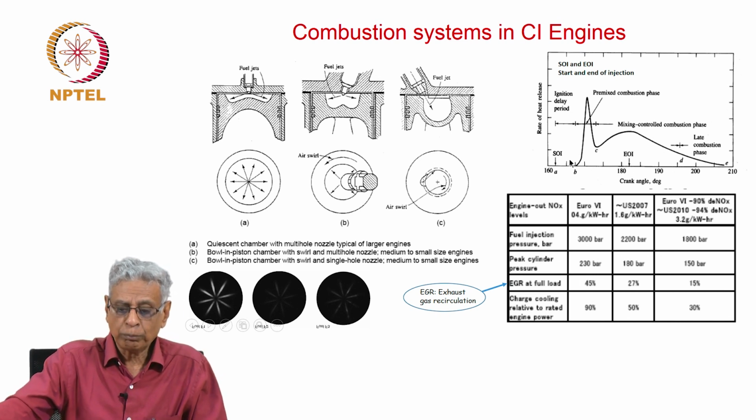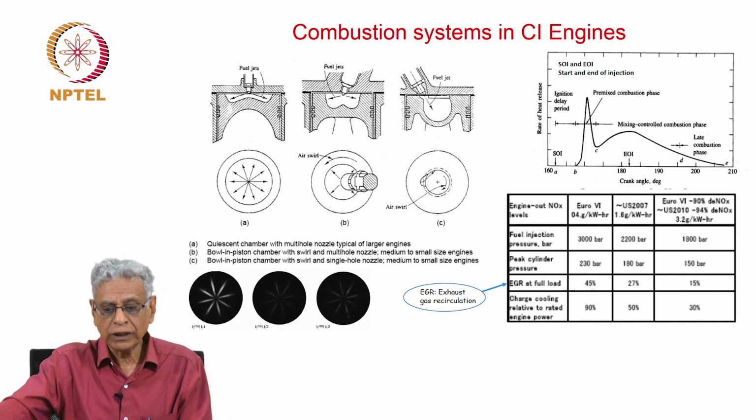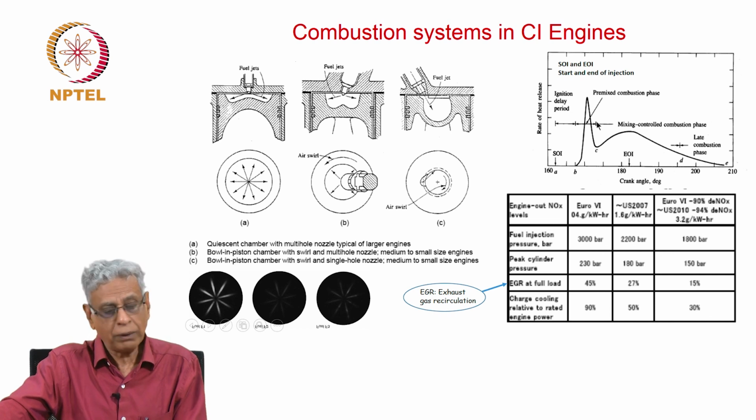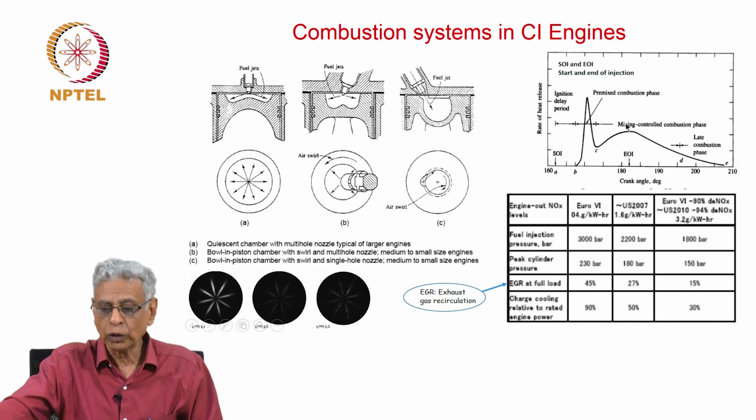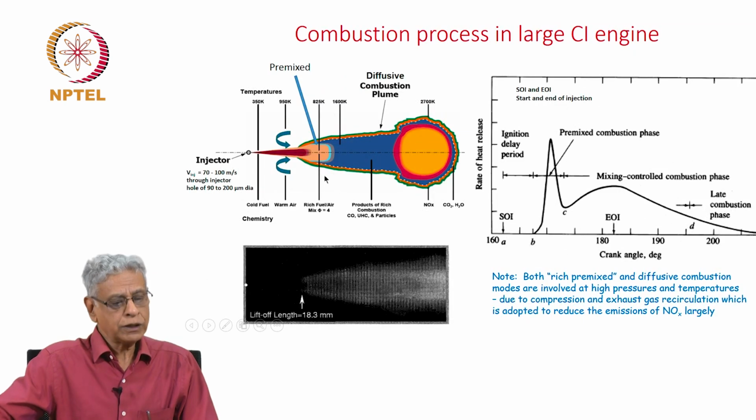And you see the actual process is, after injection, at some point of time ignition begins, and because there is a delay after injection, there is premixing which occurs. So, there is a first part which is essentially a premixed combustion phase. Subsequently, there is a diffusion combustion phase, which is also the mixing controlled combustion phase, till it ends at some point of time. These are physically described here.